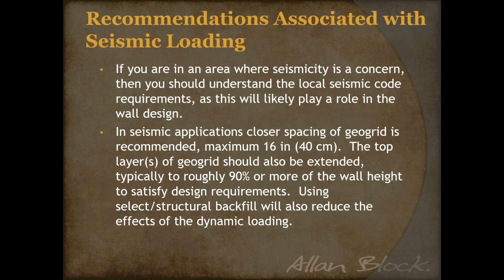requirements. We actually use AASHTO code whenever we run our seismic analyses, and we know those parameters pretty well, and we know how to incorporate them into our software. I'll show you later on how you do incorporate a seismic load into AB Walls. But just make sure that you're running the correct code and you know how to find the correct values.